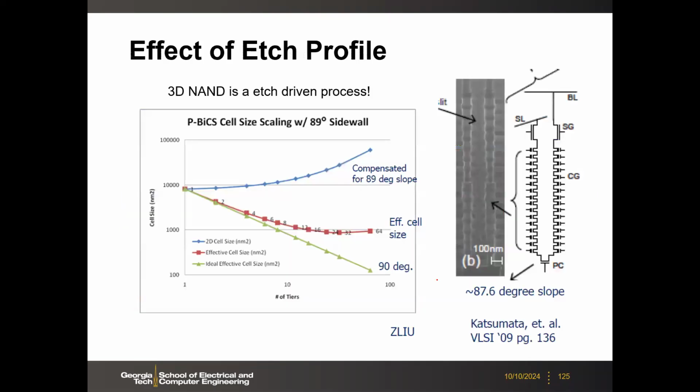So here, what is important then is you have to etch this very precisely. So if you have some angle to etch this trench, actually you will lose the density advantage, because at the top you have to use larger area. So this is not good.